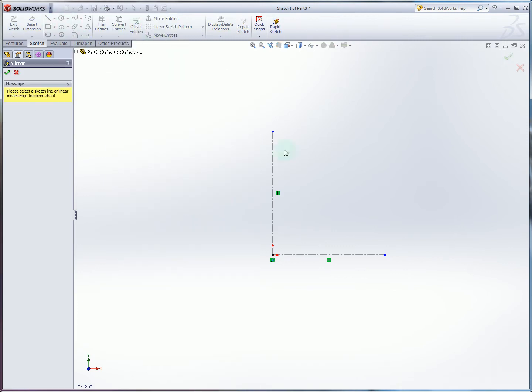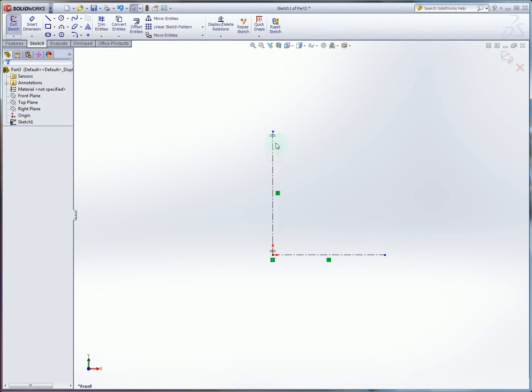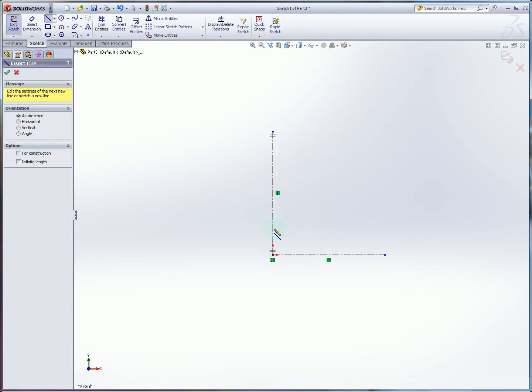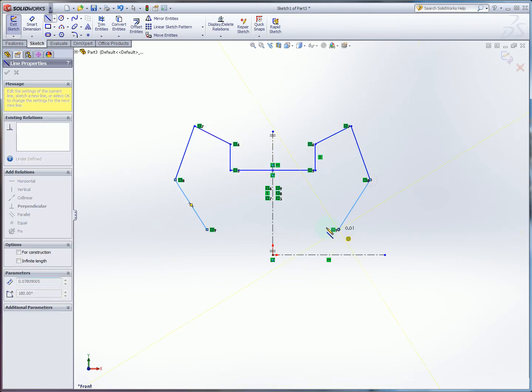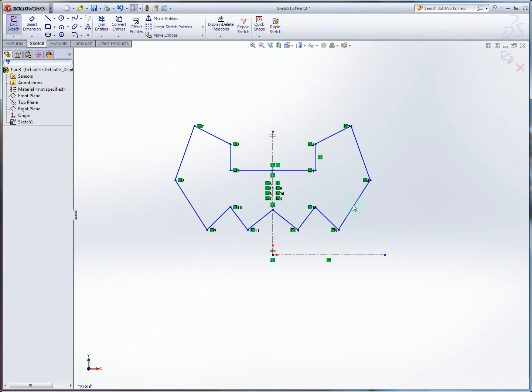What this effectively does, after we select a center line for the sketch, we see these symbols appear. The Dynamic Mirror basically lets you create lines and sketch objects and have that same mirroring process happen step by step. So instead of waiting till you've drawn your complete object on one side, you can get it piece by piece. Which you prefer is a matter of personal preference, of course. There's no inherent advantage to either one, except that the dynamic one gives you a more alive preview, so especially if you're new to SOLIDWORKS and sketching, it can be a little bit more friendly.